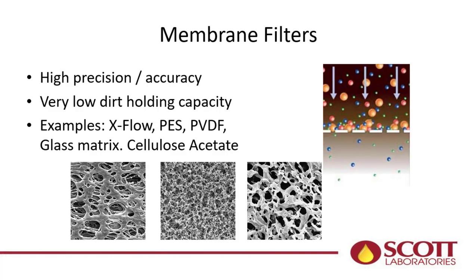But membrane filters, again, these are those cartridge filters, long skinny ones. They really have a high precision and accuracy, very low dirt holding capacity. These are just your very, very last stage of filtration going to bottle.